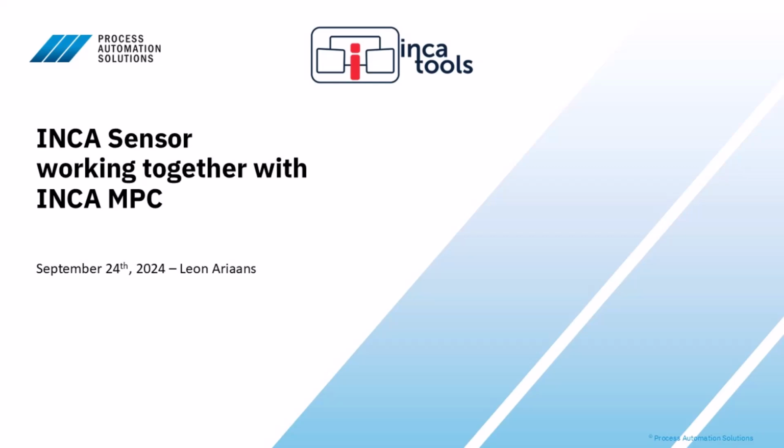That's MPC. For soft sensing, the sensor configuration consists of two parts, the old model and the tuning parameters there. The list of tuning parameters is not that long. You will have to manually transfer them from the old configuration to the new one. The models that are in the old sensor need to be converted to the form of models that the new sensor uses, but there's a tool for that, where the old model goes in and the new model comes out.